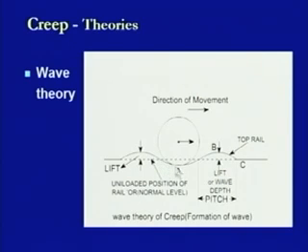So, the rail section has gone down like this at point A, that is the point of application of the loading. Now, when this has gone down in this form, a reverse curve gets formed like this. This is a reverse curve. It is having a reverse curvature on this side as well as on this side. This curvature is having a point of center in this direction, whereas this curvature is having a point of center in this direction. That is why this is a reverse curve condition.